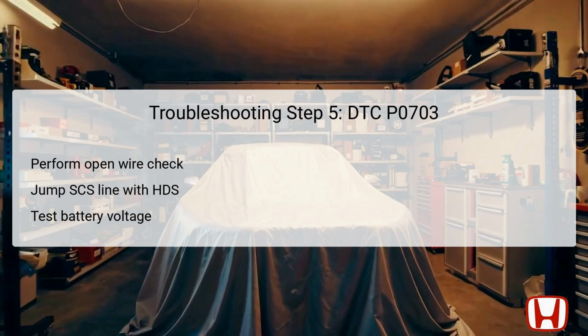Then, turn the vehicle on and measure the voltage at the PCM connector number 24 versus the body ground. If there is a sustained battery voltage, it signifies that the cancel SW wire is in proper condition. Thus, further checks or even a known good PCM should be considered. In contrast, any absence of voltage leads to an immediate necessity for repairs on the wiring.